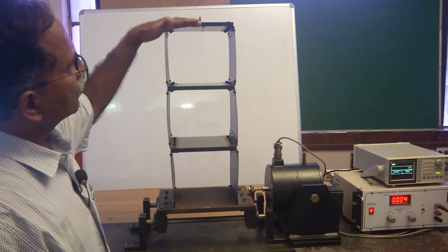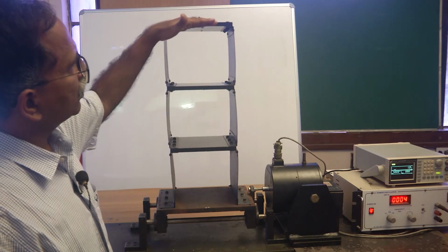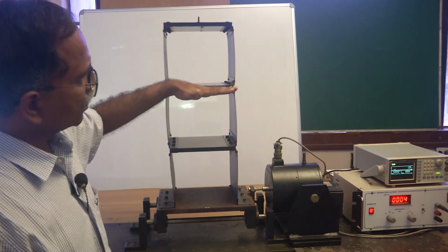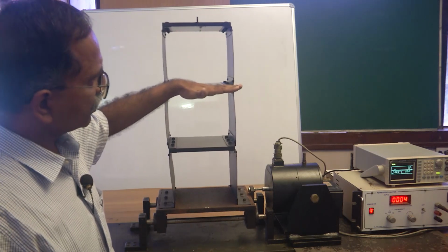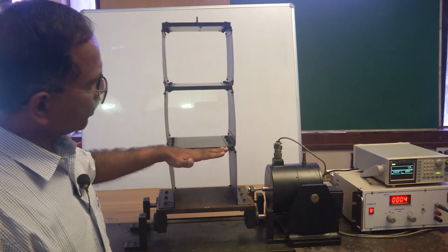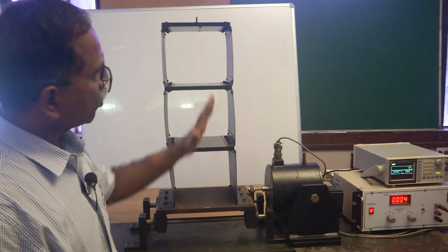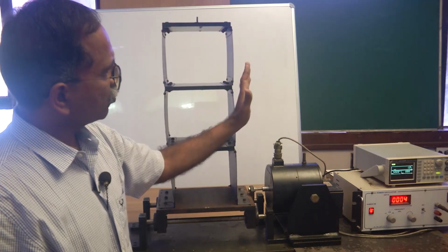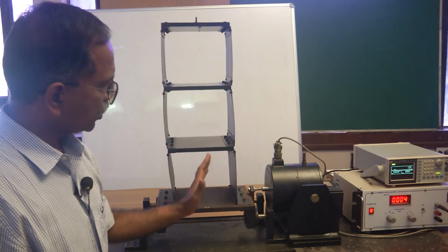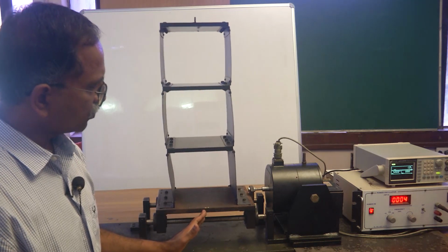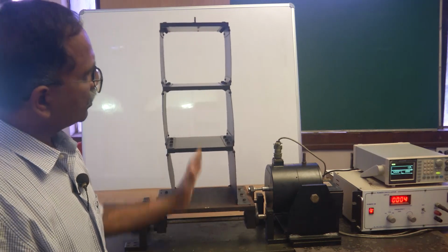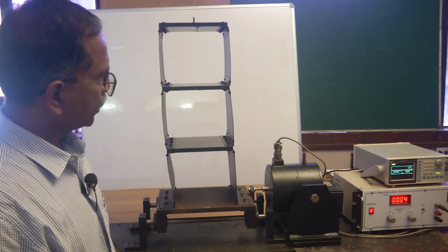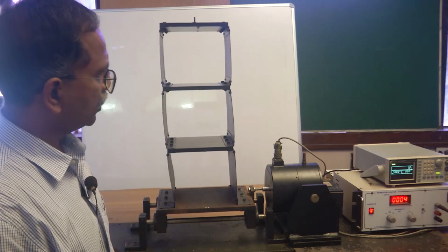You will see that this amplitude, if normalized to 1 unit, is let us say 0.7 or 0.8, and this one will be roughly 0.4 or so, and all of them are positive, meaning that when this moves 1 unit, this moves by 0.8 units, this moves by 0.4 units, and this of course will be 0. So, now this is basically indicating the first mode response, and this is the resonance that we are observing here. Okay.